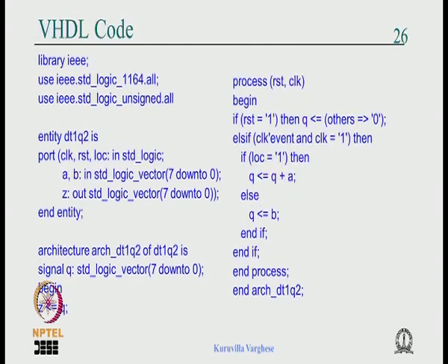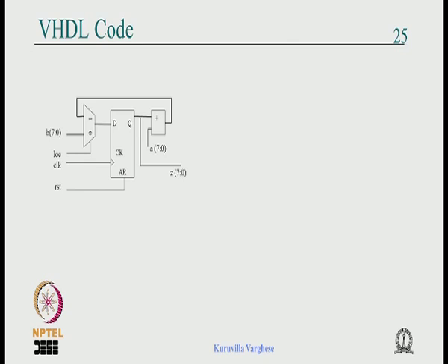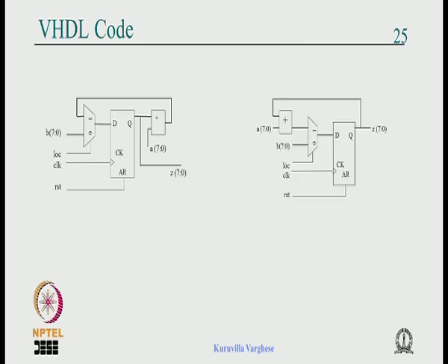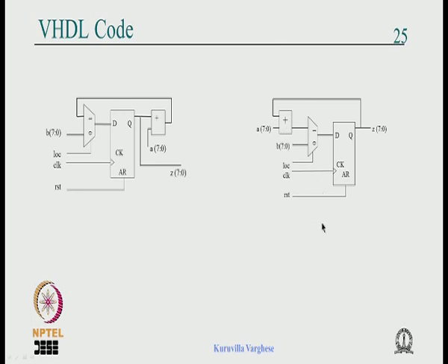Now let us do the opposite. Here what we have done is that we have been given the circuit, or known the circuit, and we have gone ahead and written the VHDL code, for very simple known circuits like the ripple adder, the carry lookahead adder, the shift register, and now some kind of random circuit without worrying about its functionality, and we have coded it. It's simple. As soon as you have the block diagram, you can code it.